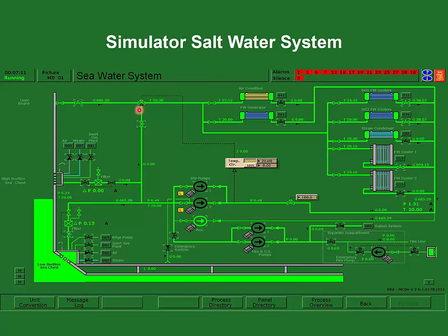This setup also has a 3-way valve and a temperature control. And this temperature control is to allow water to recirculate back to the suction of the pump instead of going over the side. And this is set up specifically for Arctic operations.